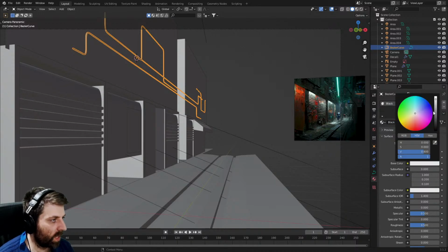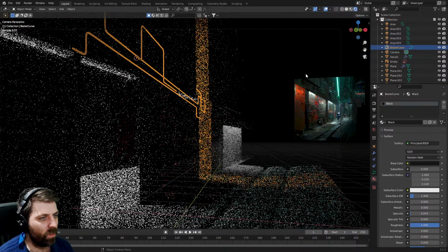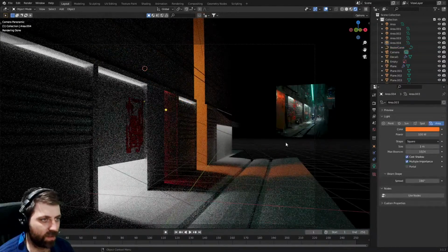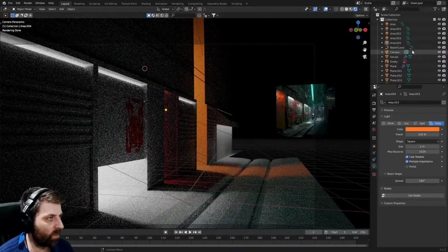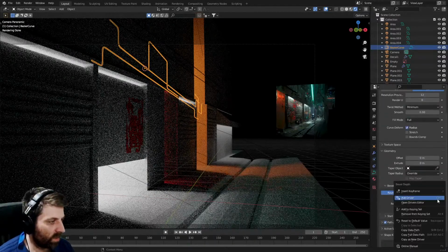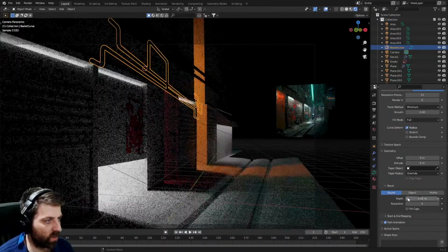Yep, whatevs. And we'll change that to maybe a dark gray. Specularity down and the roughness up. What are we looking like now? I think that's a bit better. But now that we've got those cables selected, what I'm thinking is let's go ahead and maybe just make them bigger.